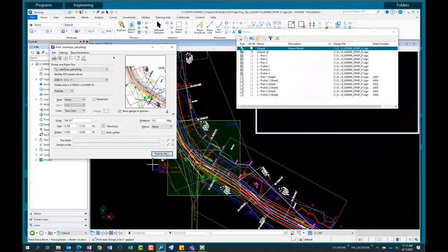It's also changed the printer driver configuration file. I like to let the printer do this automatically by applying a print style. It will automatically select the PDF printer driver configuration file. You normally don't have to do this. We haven't had to manually make these settings actually for quite a number of years. So I recommend choose a print style and then modify so that you get the look that you're looking for.